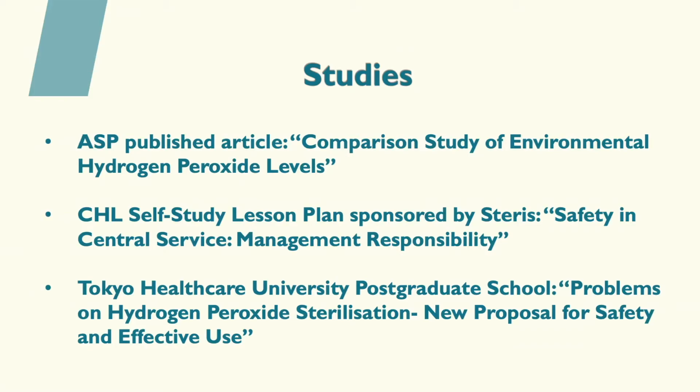There's also a study from several years ago, but it still used sterilizers that are used today. They measured the hydrogen peroxide concentration inside a sterilizer immediately after the end of the cycle. When the healthcare worker reached in to remove the load, they found high concentrations between 13 and 60 ppm. They also found that sterilizers sometimes emit high concentrations of hydrogen peroxide when they exhaust, even though it passes through a catalytic converter. So again, these machines are built to high spec, but sometimes the hydrogen peroxide escapes anyway, or sometimes there are malfunctions.